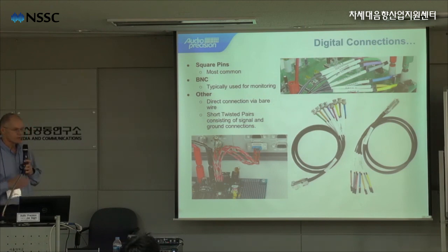It's buffered, and it uses a Schmitt trigger, so it's going to have the same timing, but it's going to be a better quality signal than you might have on your device under test. And we also have this optional short. I think this was made by someone for a special project, but we have a variant of this that we sell as well.